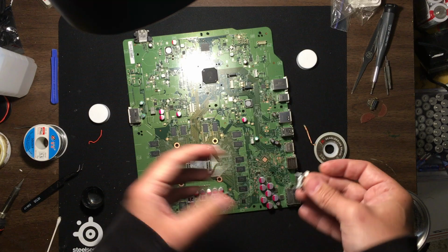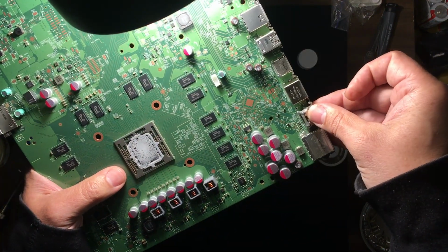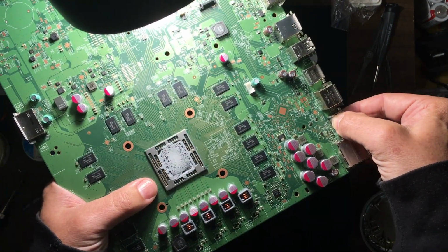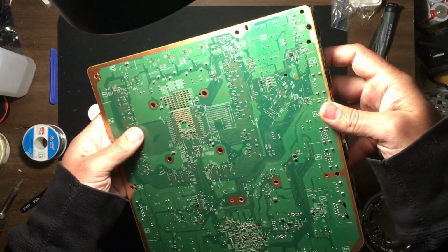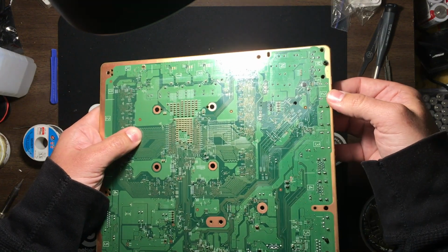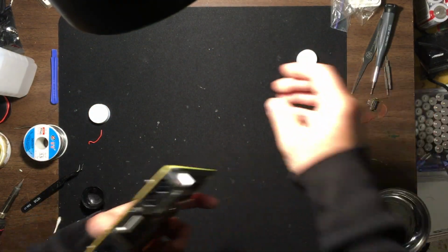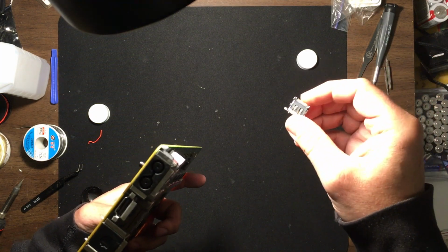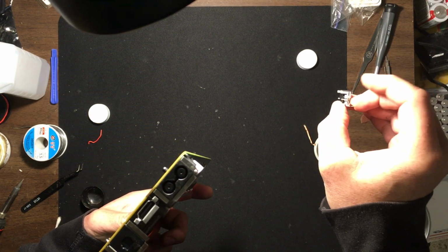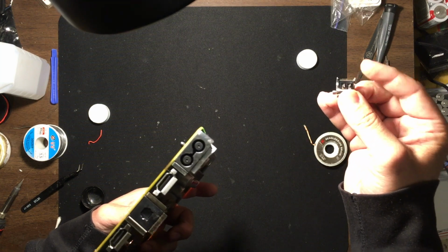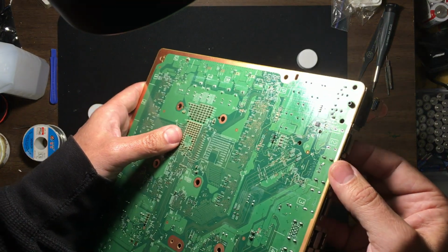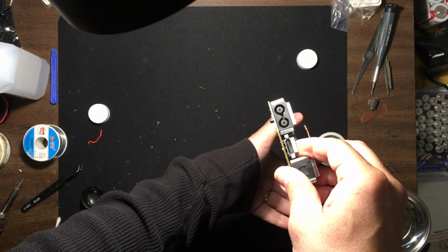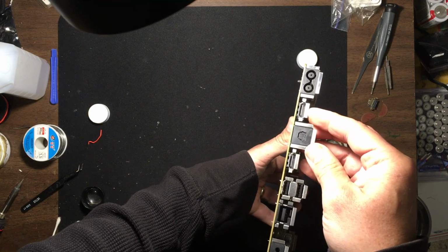So what we're going to do here, with the holes cleared out, is pop this guy right into place, put all of our legs in, and then push it down. On the other side you can see the legs popping through, but there's also plastic on the bottom. The plastic, or this black part, actually makes contact with the motherboard, and the metal comes through. We would solder these pins down to hold the port in place. We'll do that in a moment, but we want to make sure that this sits flush. You can see it sits flush, just as it does here.